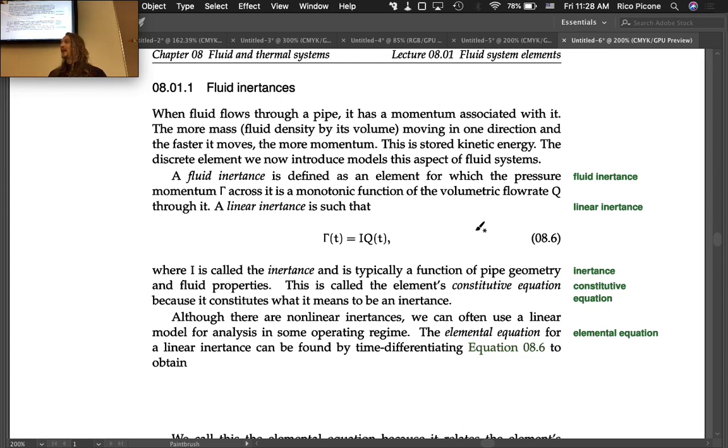Even a small pipe that doesn't have a ton of pressure behind it can burst if you do that. Slowly shutting the valve off is what you want to do. Slamming a valve shut is not what you want to do. It's because of this pressure momentum. It will create this big pressure wave in the pipe. And that's what we're going to try to capture here. We're saying, oh, there's a lot of energy that's stored in that fluid that's all moving in the same direction.